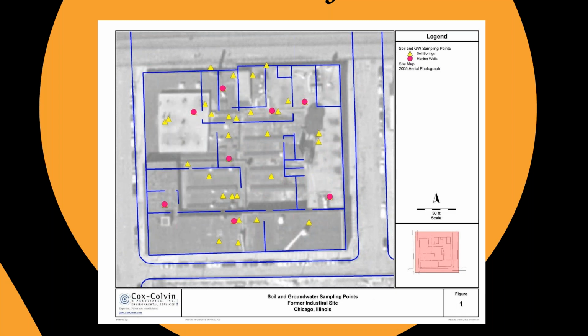So if you look back at where they had done their work, you see they just avoided that whole area. They had one soil sample basically from the area. And the reason that they didn't investigate that area much was it was a reception area in the current building. But if you looked at the history of the site, it was a machine shop in that part of the building. So it's important to tie the history of the site back to what you're doing so you can make these kinds of predictions about why things are where they are.